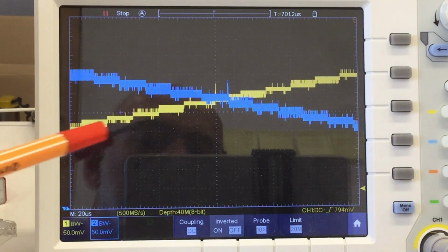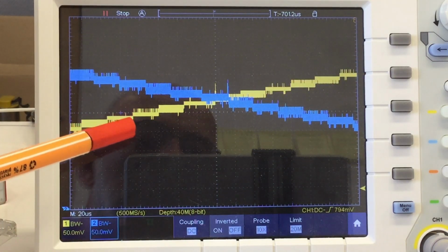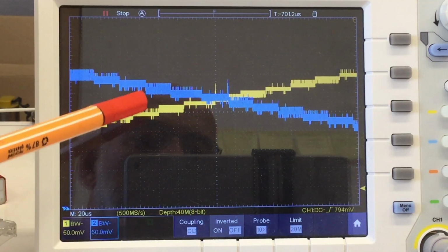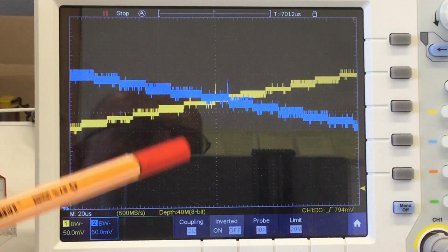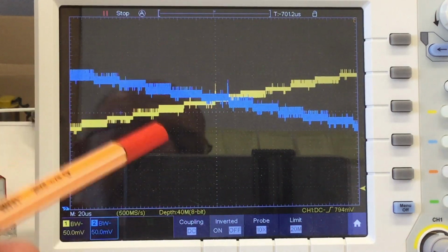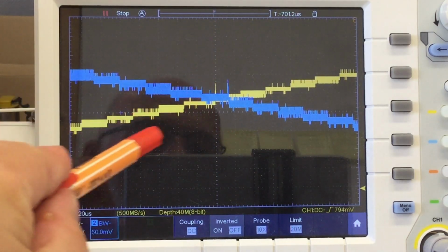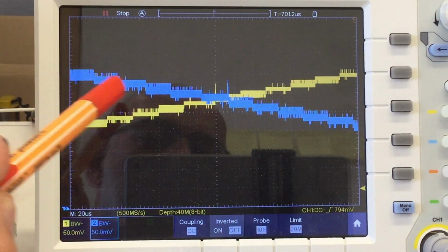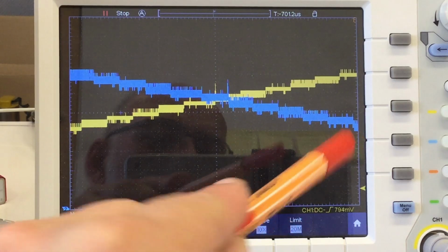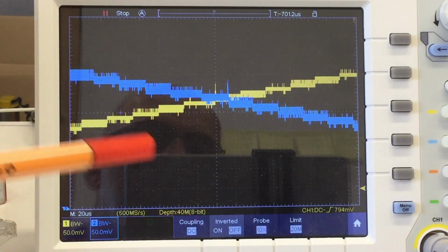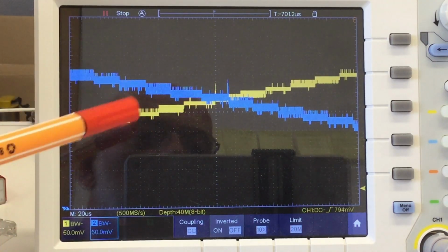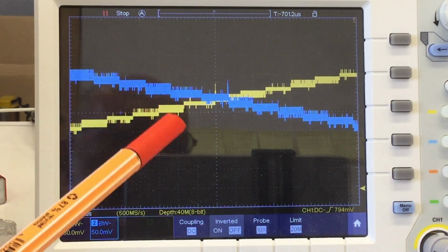In fact, channel A changes its value a little bit earlier than channel B. And that's a natural product of how we drive that DAC over SPI. We first send a value for channel A, and then we send a value for channel B. And in some applications, this little delay between the two channels can ruin your day.